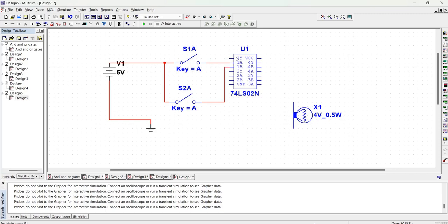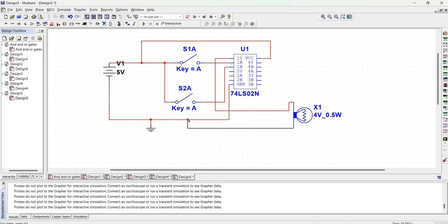Okay, that is for a NOR gate IC. This is pin number 1, 2, 3. So 1 is for taking the output. So we pick our output, take it to the indicator. Then we also connect this VCC or the pin that accepts power. We also connect it to our source of 5 volts. Now this ground must be connected to the ground of the circuit. Also, from this indicator, we shall connect the ground. Now, our IC or circuit is already complete.